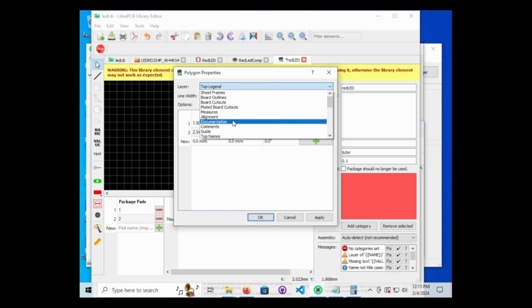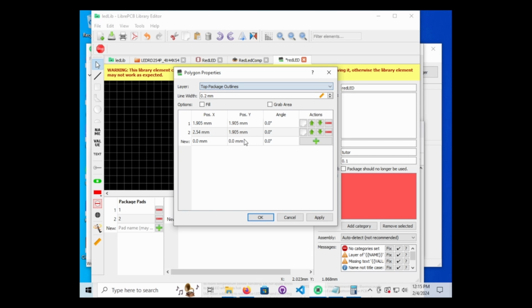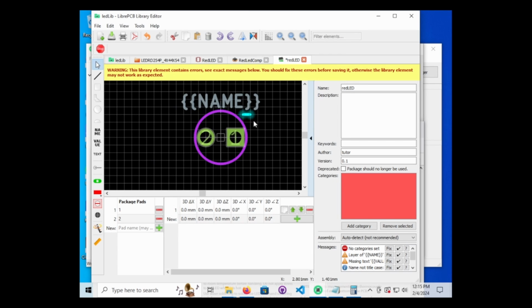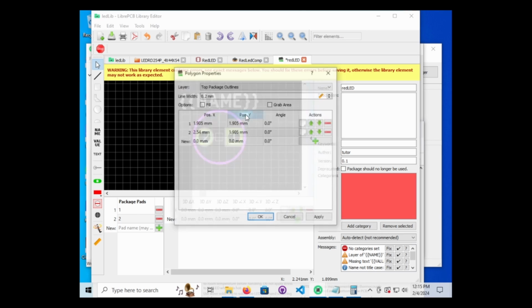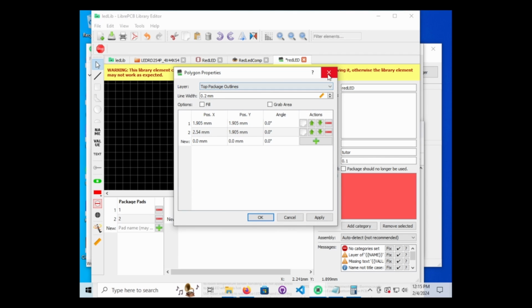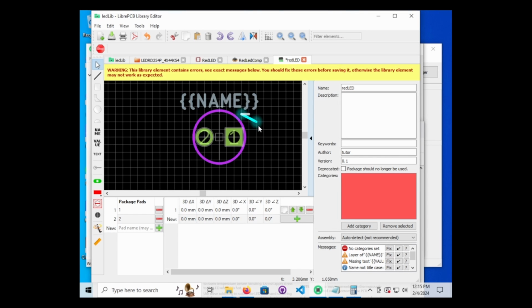Because usually you'll sometimes see the diodes and they'll have a flat side with a circle. And that's indicating the same thing, cathode side. There's just a couple different ways to indicate it. We're going to put it on the same two layers that we put the circle, our little top silk screen layer, and our top courtyard. Courtyard's usually used for PDFs, and silk screen is for printing onto the board.